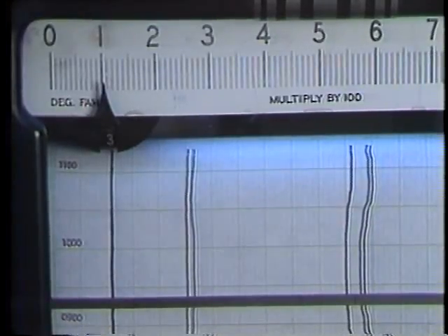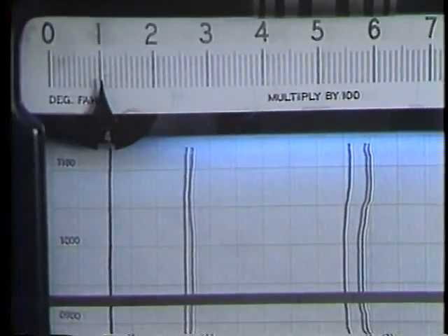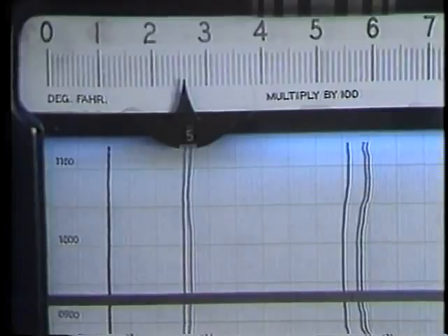Similar action is required to deal with the loss of air preheaters. Most boilers have two air preheaters which are used to increase the temperature of combustion air before directing it to the boiler. The symptoms of air preheater failure include a decrease in the air temperature leaving the air preheater, and an increase in the flue gas temperature leaving the boiler.